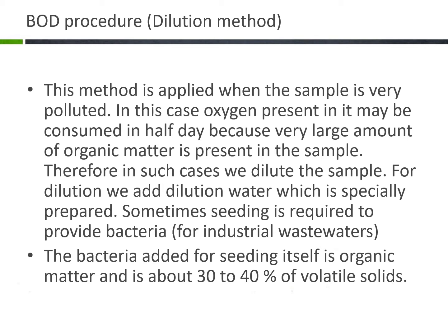So we will prepare different dilutions and see which dilution works, and then we will use that dilution for our experiment on BOD. Then we will multiply the answer by the factor of our dilution so that we can get the original value of the organic content.